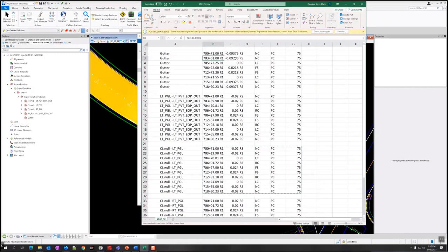If you look at the table on step 3 of this exercise, on page 3-17 at the top, it kind of explains what the transitions need to be. For these transitions, the standard plans spell out a lot of what it needs to be. For the gutter, it doesn't spell out necessarily what it needs to be. It just spells out that it needs to have a transition. It implies that there's a transition because you can't just jump from 0.09375 to 0 and then go from there.